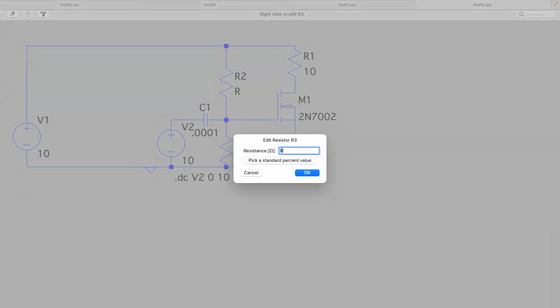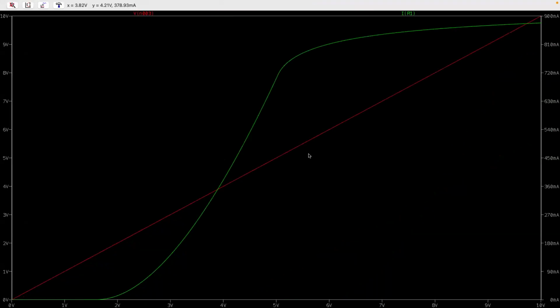So when you come here and you're trying to find the resistance, you look at that graph. You'll find the linear region. So let's say right here in the middle, and then you'll just draw a line straight down, 4 volts, 3.9 volts, something like that. And then you're going to do a really simple voltage divider.